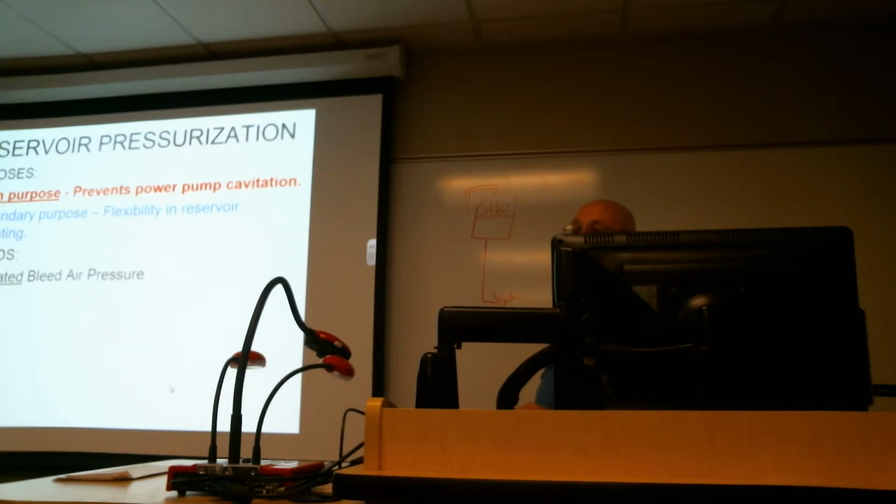As those vapor bubbles collapse, it imparts a tremendous force on the pump that's extremely damaging. So I'll send you a video that's very important. So by pushing on that fluid with an artificial method, we can prevent cavitation from occurring. So it's a substitute for air pressure that you normally have at sea level.